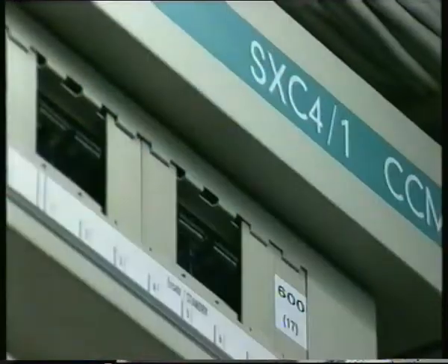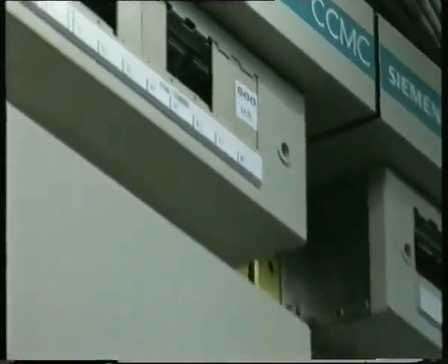Ports on the switch are at STM1, but the 4.1 will demultiplex the STM1 signal and then switch circuits at tributary unit level. In other words, a 2 megabit circuit arriving in the payload of one STM1 signal can be cross-connected to the payload of any other STM1 signal on the switch. This is sometimes called traffic grooming. As you can see, the 4.1 cross-connect consists of a number of racks of equipment.